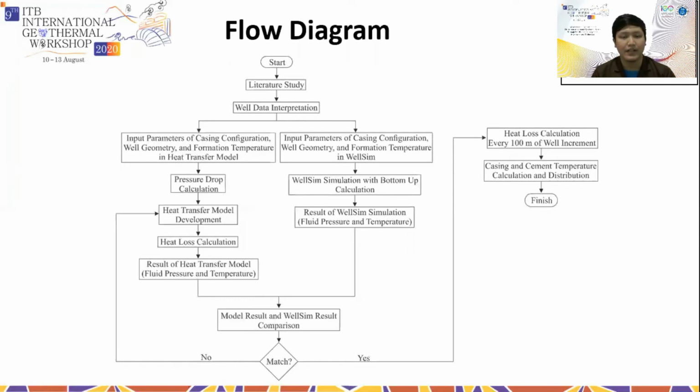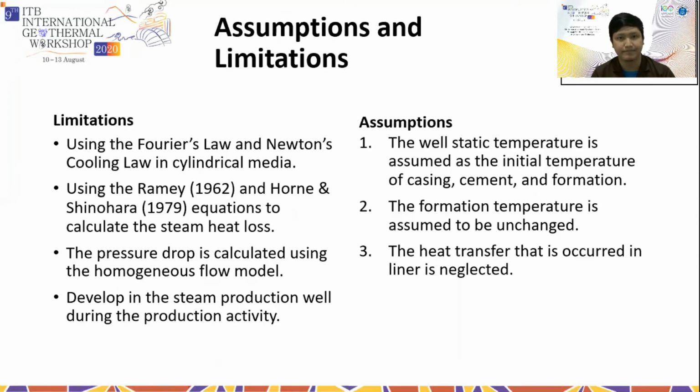If the model does not match the WellSim result, we must check the heat transfer model development, such as the equation of heat transfer or the input parameters to the heat transfer model. And if the model matches WellSim, we can continue to the next calculation, such as the heat loss calculation every 100 meter of well increment, and the casing and cement temperature calculation and distribution.